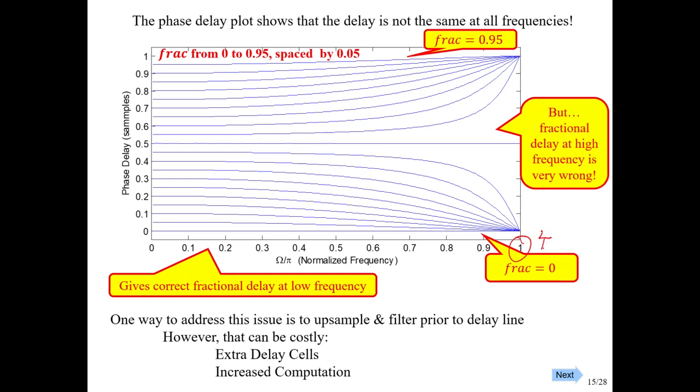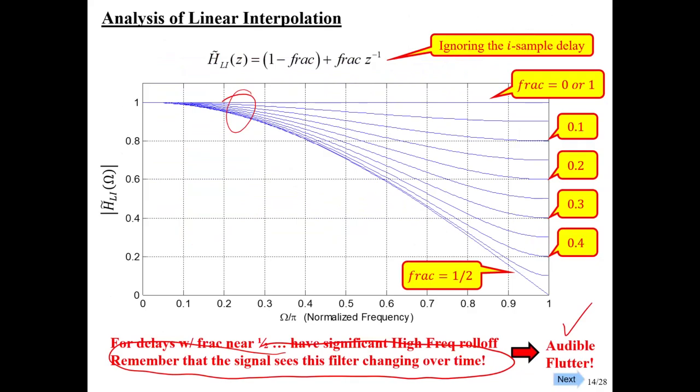Our sampling rate might be on the order of 80 kilosamples per second. So Fs over 2 is 40 kilohertz. This is 20. This is 10. This is 5. Really good. Let's look over here. Now we're down to here. We still get a little bit of fluctuation, but not that much.